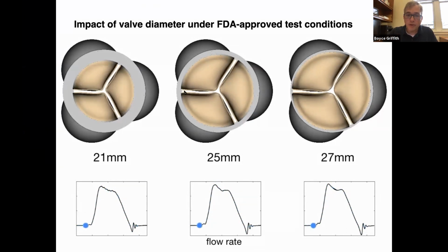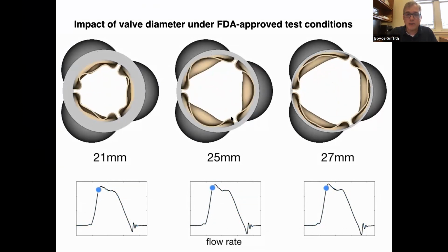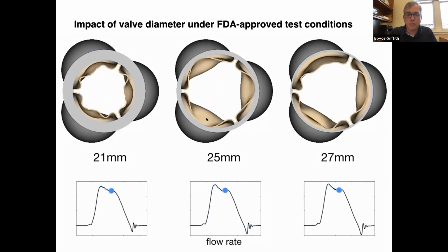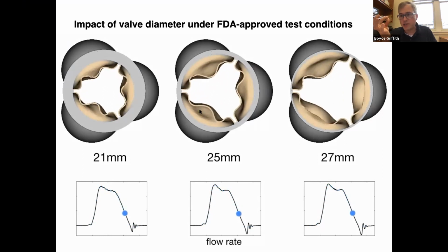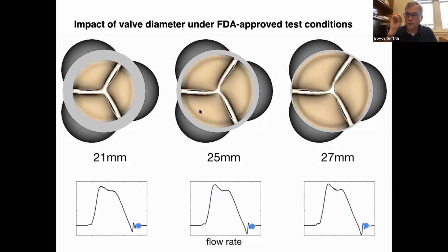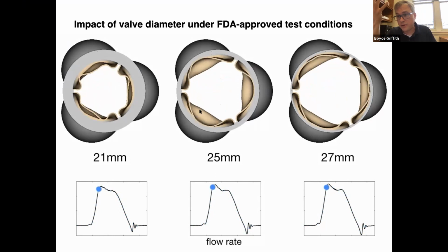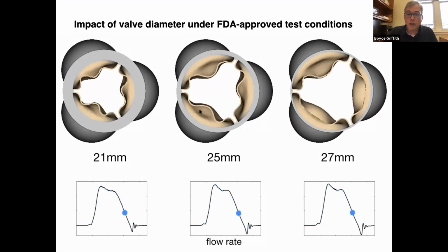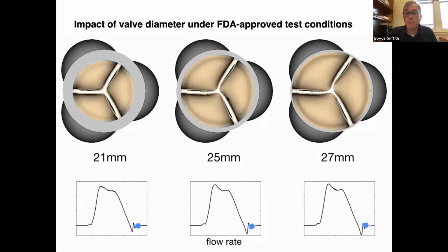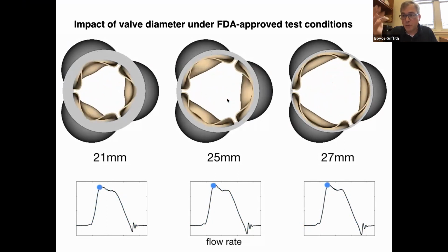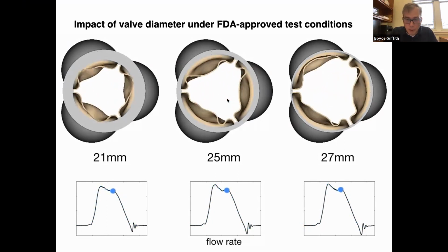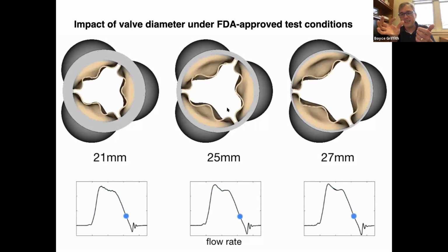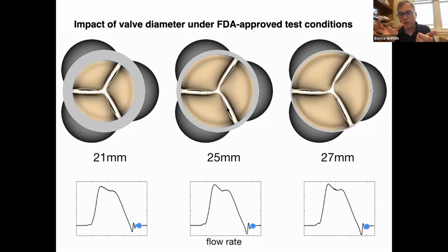You can think of there being forces that are concentrated in the structural model just along the volumetric mesh that we're using for the leaflets, but those forces get smeared out over an additional volume that corresponds to this regularized delta function. So here what you're seeing effectively is the background grid resolution. The leaflets are ending up about a mesh width apart or so. But you have a contiguous force that shows up.